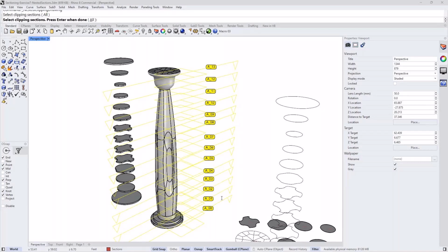Yeah, this has many applications. People build things out of styrofoam that's cut with a vertical hot wire. So it's basically a three-axis operation. You don't have the ability to tip the cutting tool. A three-axis CNC mill or CNC router is the same kind of thing. They're all the same type of operation, and you end up with slabs that are stacked together, and then you somehow, most usually manually, blend those slabs together to get your final object shape.